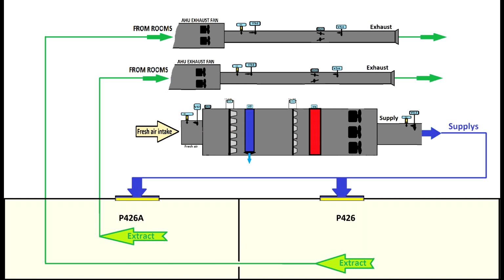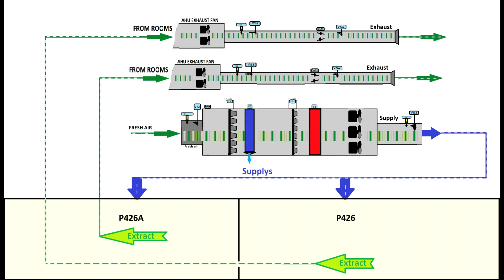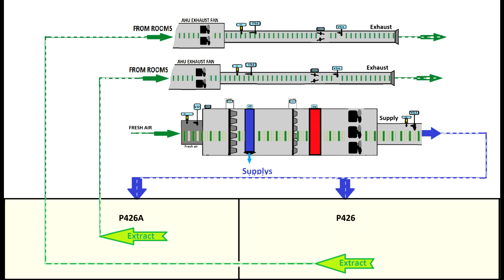And if you look carefully, zooming into it, you'll see there are a lot of sensors which collect data, and the data goes to the PLC, so the PLC will control this air handling unit. Now what you'll see here is the air circulation through the air handling unit, and this air handling unit has 3 motors. Later on you'll see they will be colored in red because they are a source of heat. So these motors actually are a source of heat.